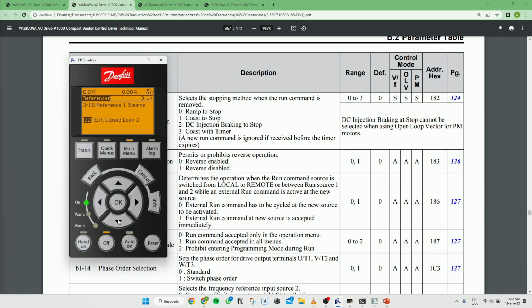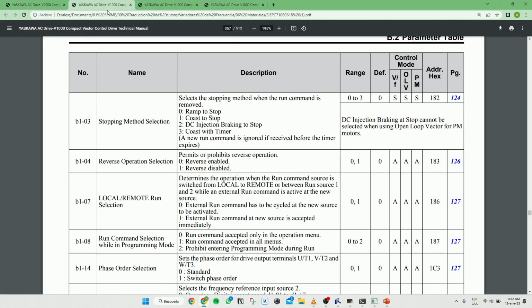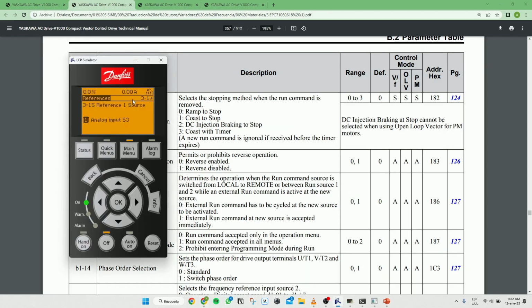And here we have our loop part, which is what I make for additional references. And this is the analog input connected to terminal number 53. This is what I consider to be first instance to use logic. So I don't have this open really. So open your navigator, your seeker, and confirm if your parameter number 3-15 is the velocity reference. And select whatever reference you wish. That's going to be your exercise.